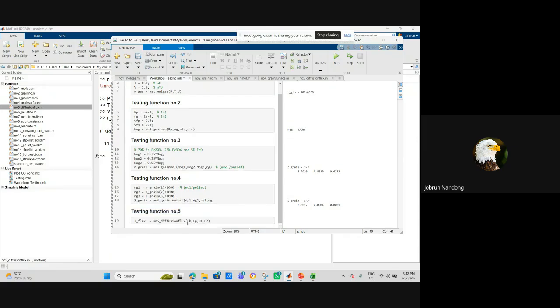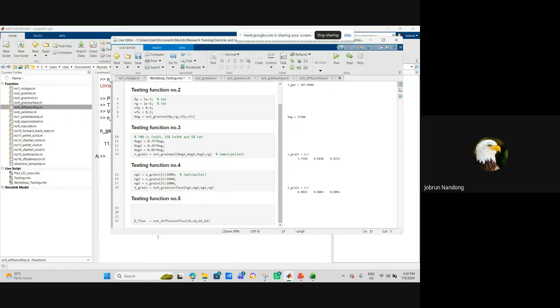So we check whether we have enough or not. We need to insert CB value there. D1, D2, all of this we need it. So what we do is that we're going to insert value first. CB is a vector, right? Consists of two values. So we write that the first one should be the concentration of CO. So let's say put 10 there, 10 mole per meter cube. The other one maybe 2 mole per meter cube. Any value just to test whether this thing work or not.